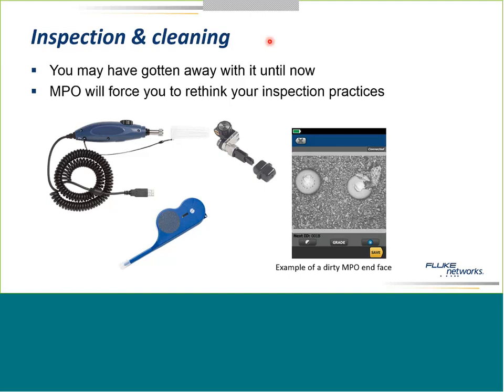Now, I've heard stories where there are going to be MPO cassettes that come hermetically sealed from the factory. They may have a white piece of plastic over the MPO port. Those are designed to be clean, and you really want to keep them that way. But other than that, feel free to inspect any MPO ports, especially MPO trunk cables, and especially LC and SC patch cords. I don't care if you just opened the bag and it just came from the factory.